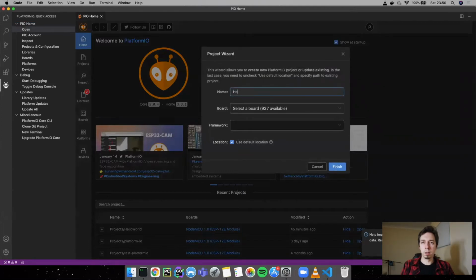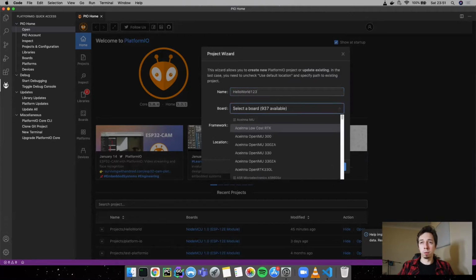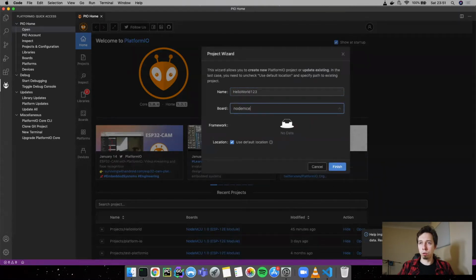I'm going to give it a name. I'm going to call it Hello World 123. And the board that I'm going to choose is NodeMCU. That's what you need to type in if you're doing it with me. And the one that we want to choose from here, you see there is Espressif ESP8266, and we want to choose the latest one. For the framework, we want to keep Arduino.